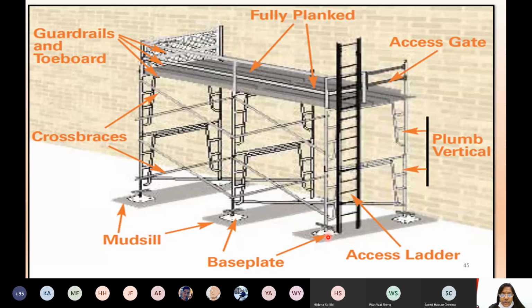And coming to the bottom portion, it's clear here. This is the bottom plate and the base plate of this fabrication. This is the formwork, and this is the mud. Just see how loosely it is kept, just sitting on the mud plate, mud sill, right? Mud packing. Onto that there is a steel base plate with the pipe welded onto the base plate, and it is erected.